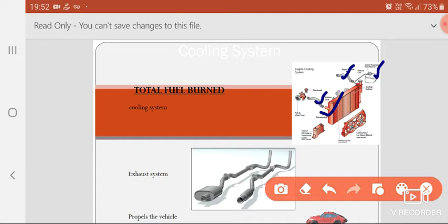In the next diagrams, you will see the details of the radiator very clearly. In the radiator, the fan is there. The fan is continuously pumping air through the radiator. So cold air being pumped through the radiator, hot coolant comes in contact with it, not direct contact, through the metal, as it works as a heat exchanger. As it comes in contact with the heat exchanger, there is a heat transfer from hot coolant to cold air. So hot coolant becomes colder, air becomes hotter. If you stand in front of the radiator, you will get hot air, because heat is picked up by the air and that is coming out. This is how the radiator is working here.